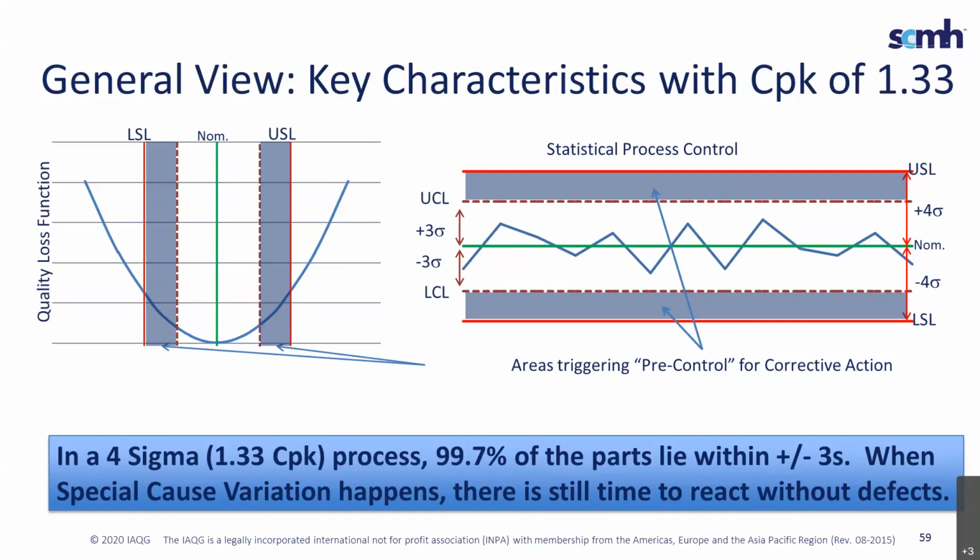And this is specifically one of the tools that we use to do that. Statistical process control is a great tool to continue to identify a CPK or standard deviation, and identify when we are successfully improving our variation reduction and therefore improving our customer enthusiasm for this characteristic. And this would be used for not only the final customer key characteristic, but also all of the process key characteristics as well.